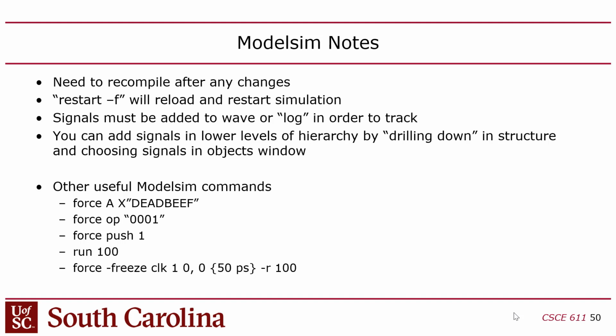So if you use a testbench, and I'm going to talk more about that in just a minute. Testbench is a way to write a module that tests another module, and it's more automated. So you usually don't have to do much with a testbench. All you do is open ModelSim and say go. That's it. And then if there are any errors, it'll probably print an error message, right? However, sometimes you don't have time to write a testbench, or you're like me, too lazy to write a testbench because you want to do a unit test of just one little thing, and you don't want to take the time to write a whole module just to test that.